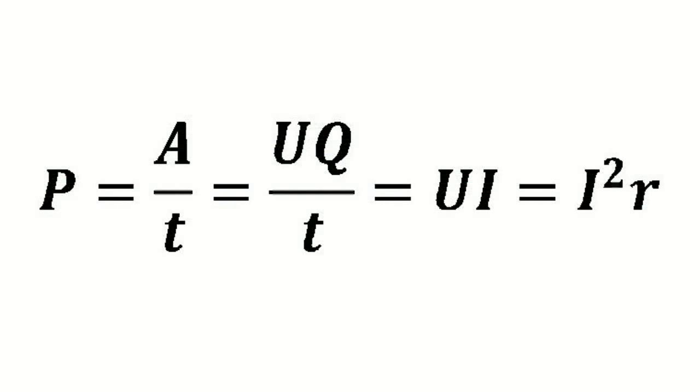It follows from the formula of power that with very low external resistance R, the amperage in the circuit is high, and the voltage at the terminals of the generator is low at that. When the external circuit resistance R is equal to 0, the voltage at the terminals of the generator U also equals 0. Consequently, the power P given to the external circuit equals 0.